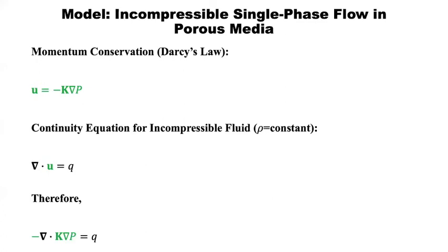Once you calculate pressure from this equation, then we'll get back to Darcy's law. Now we assume that we knew pressure by solving the last equation, right? Yes. So we'll substitute back in equation number one, the first equation, Darcy's law, and we'll get velocity.